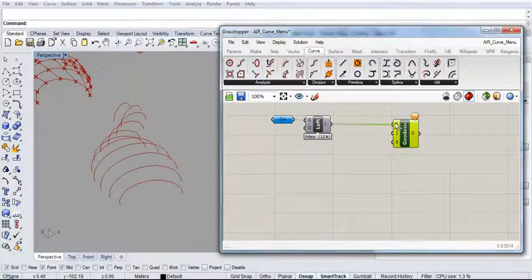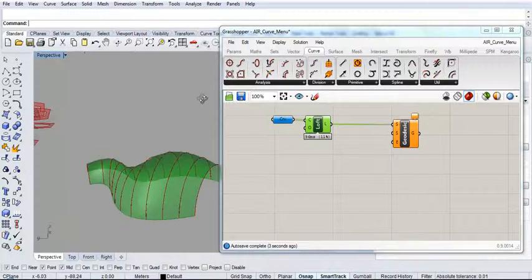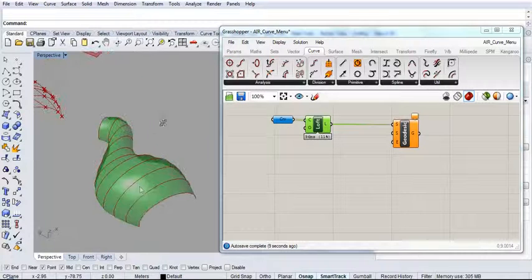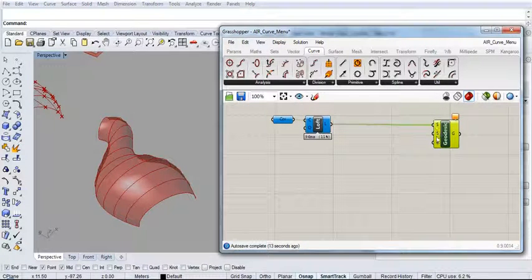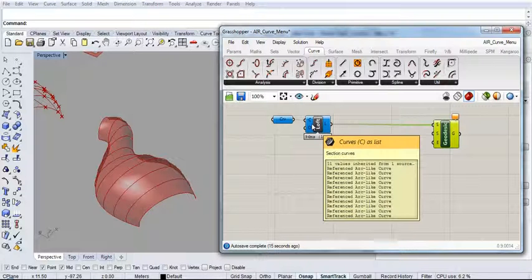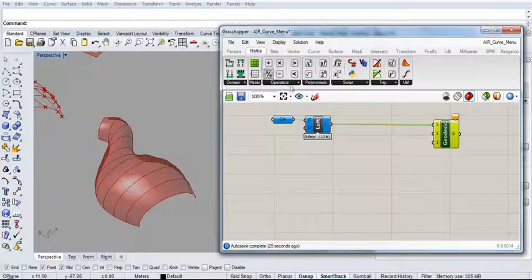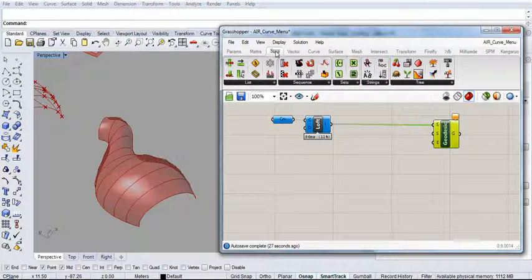We need a base surface geometry, so I'm going to use our lofted list of arcs that we were demonstrating previously, and we need a start and end point, which both already exist on the surface. So I'm going to use a clever trick to create start and end points on the surface, which will be covered in later tutorials on understanding parameter space and some of the maths or sets components.